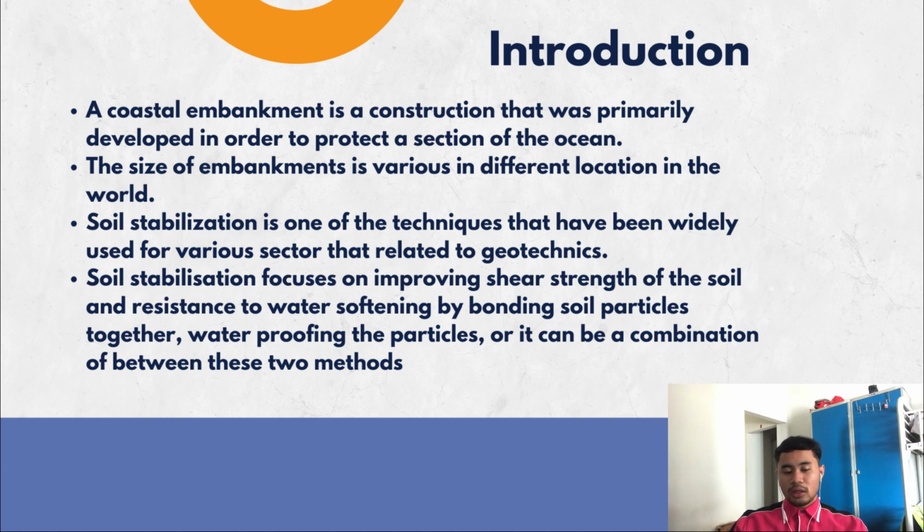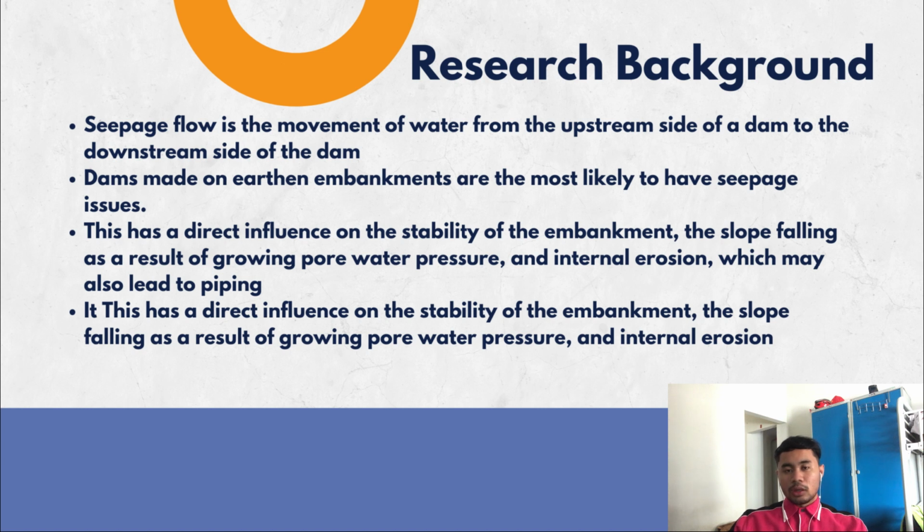So soil material can be stabilized with cementitious through soil stabilization like cement, lime, fly ash, bitumen, or combination of those. So the method is accomplished in two ways, that is in situ stabilization and ex situ stabilization. So it is important to know that stabilization is not an instant solution that can improve all soil properties. Next, I will present to you about my research background.